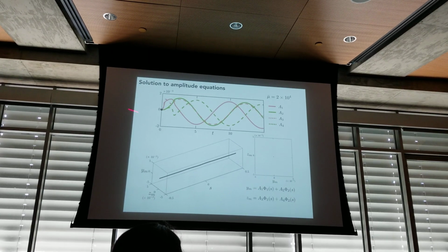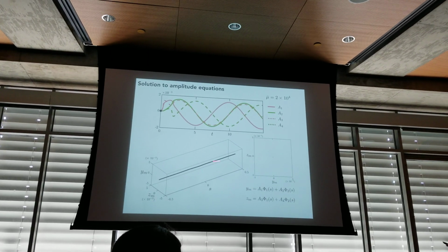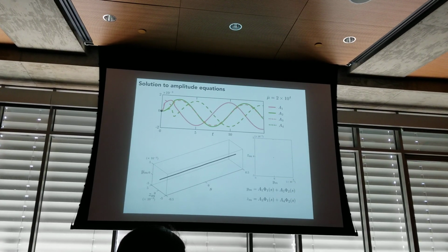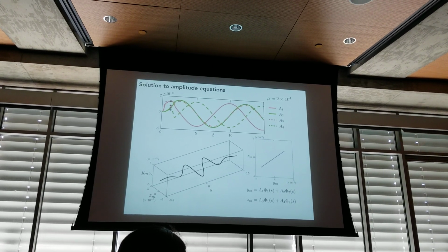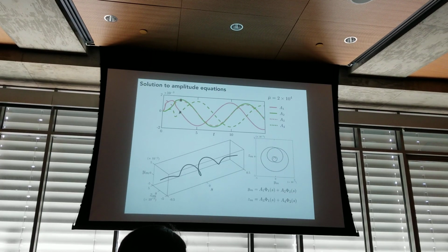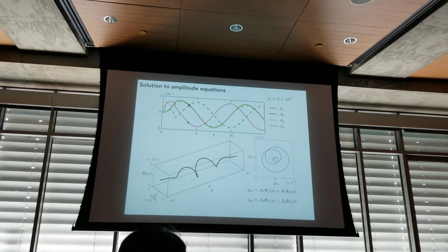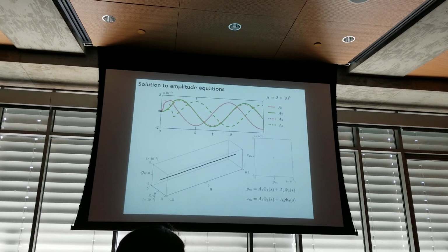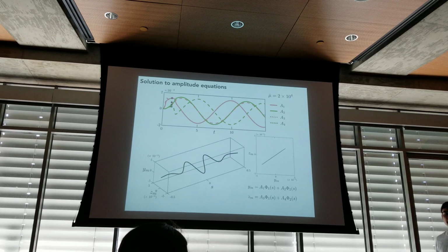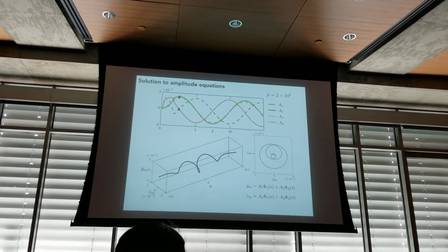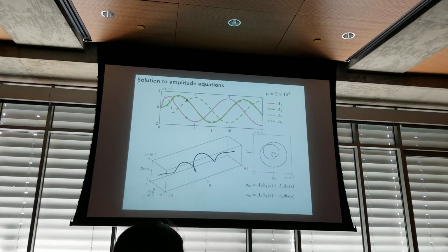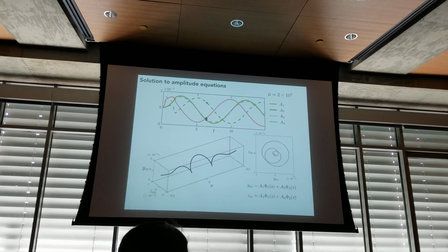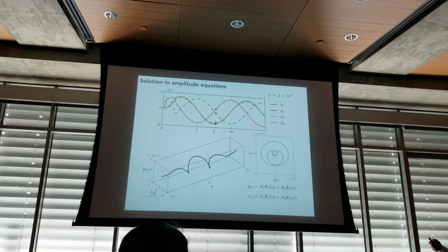We plot the amplitude as a function of time, and over here I plot the filament conformation, and this is the projection. So let's take a look how this works. You see there is buckling, the conformation remains planar, and then there is nonlinearity kicking in, and there is a spontaneous symmetry breaking that gives rise to this helical structure. So let's play that once more. That's planar buckling right at the onset. That's because the mode shapes are identical on this orthogonal plane, but then the nonlinearities kick in, and that allows these adjacent modes to interact, and this is what is giving rise to this helical structure.